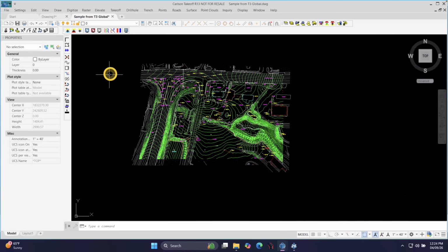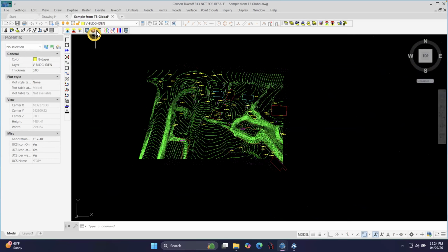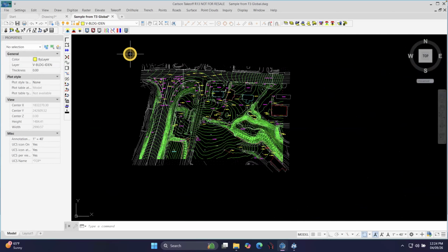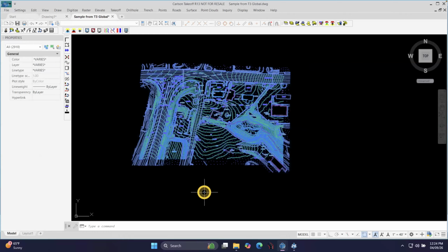Takeoff, if you use that color designation, which is real nice to be able to quickly see what's existing, what's designed, what's other, as well as this toggle on and off, turn off the existing, turn off the other, get the clutter out of your way, that's why they're doing that by color. And that may be how you do your work. But if you want to ever set that thing back, then you would simply select everything if it's all displayed, which it is. And up here where it says color, I'm going to set that for every item there.